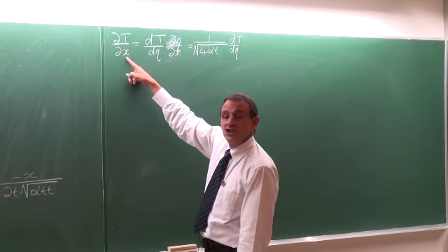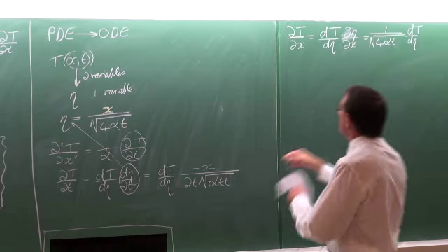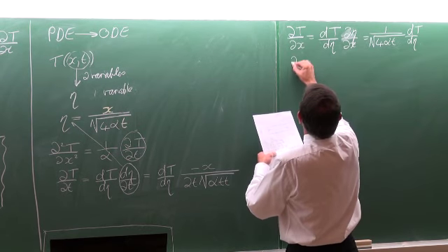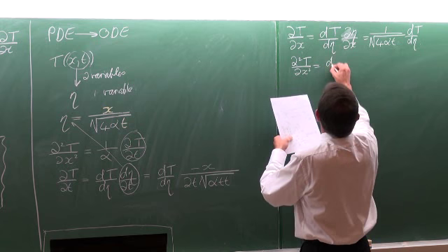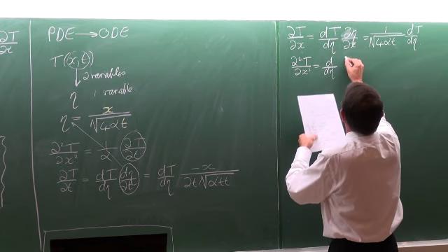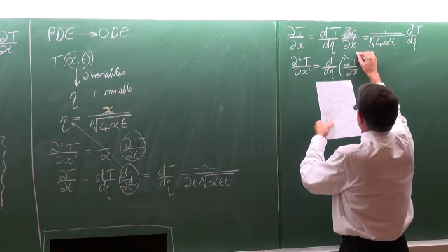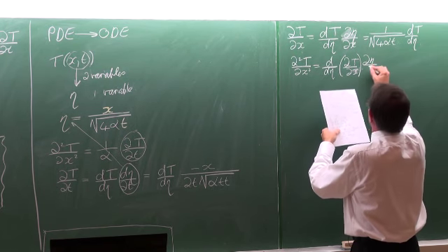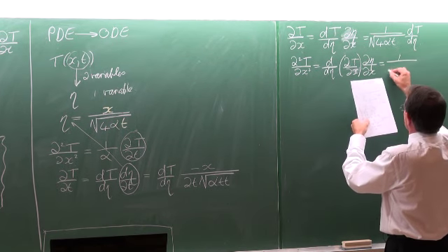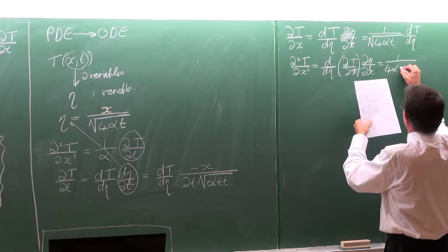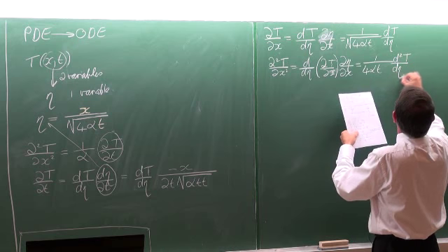Okay, so that would be for ∂T/∂x, but we actually need ∂²T/∂x², which we can write as ∂²T/∂x² is equal to ∂/∂η of ∂T/∂x multiplied by ∂η/∂x, and that is equal to 1 times 4 divided by αt multiplied by ∂²T/∂η².